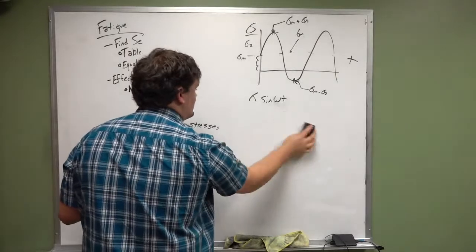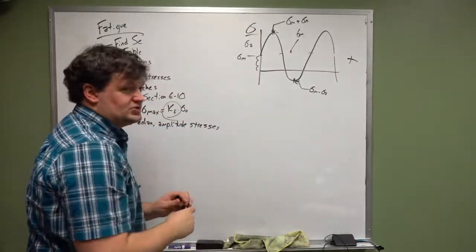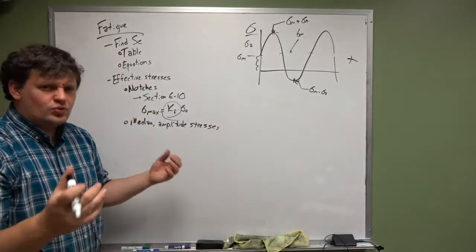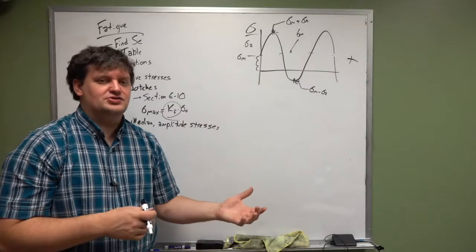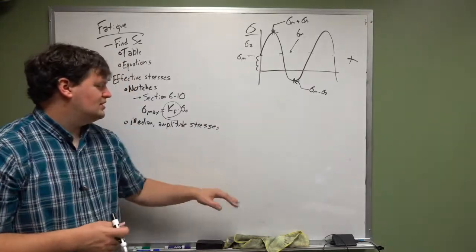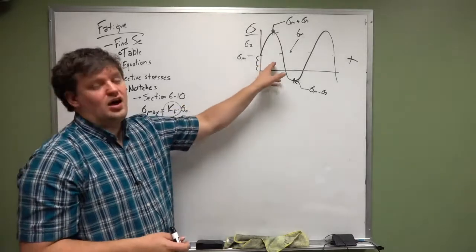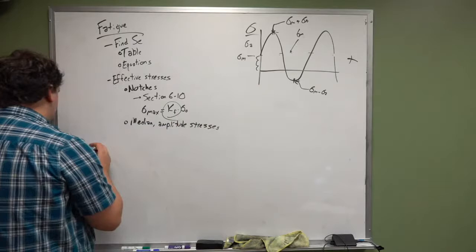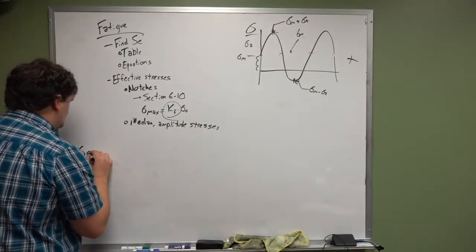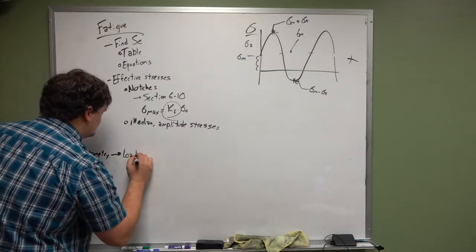Last time I showed you the process for stress with a fully reversed loading situation. Now we're going to add one little simple step that will help us understand what the stress conditions are with a non-fully reversed loading cycle. First you start out with your geometry, just like last time. You figure out your loading.